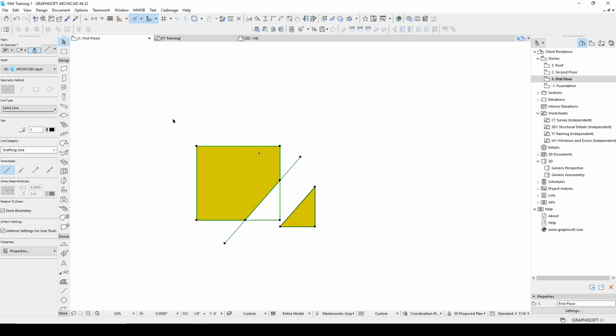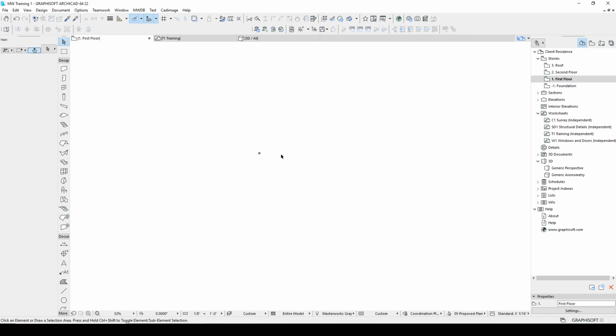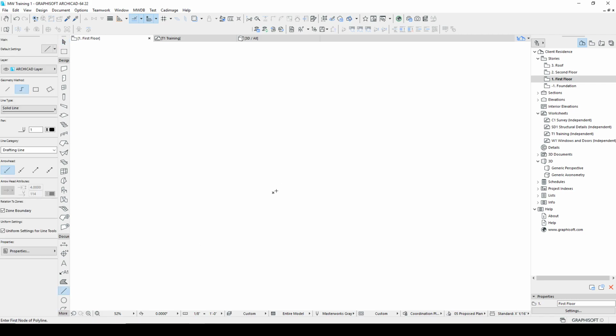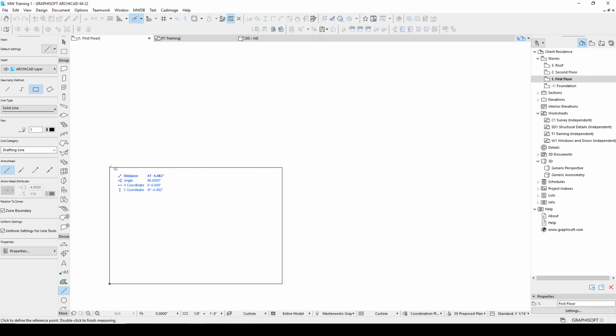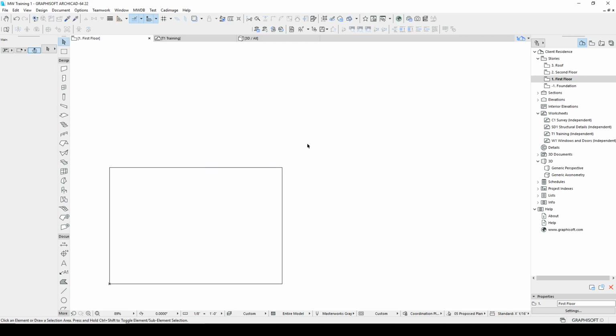And the last feature I want to teach you in this module is one of my favorites. And it is moving the user coordinate system. So let me draw a rectangle here. Let's say I want to draw a line starting 1 unit over and 1 unit up. Let me check my scale here. So this is 60 feet. So let's say I want to go 10 up and 10 over.